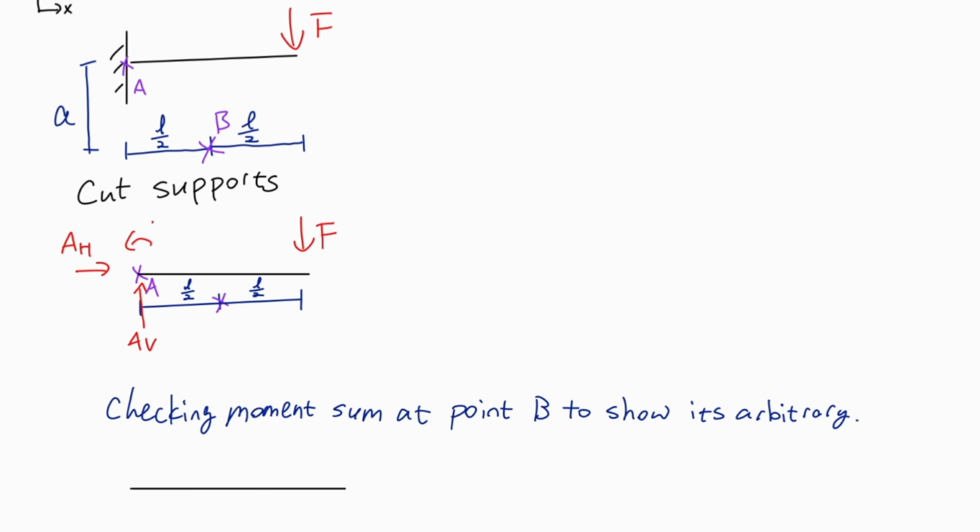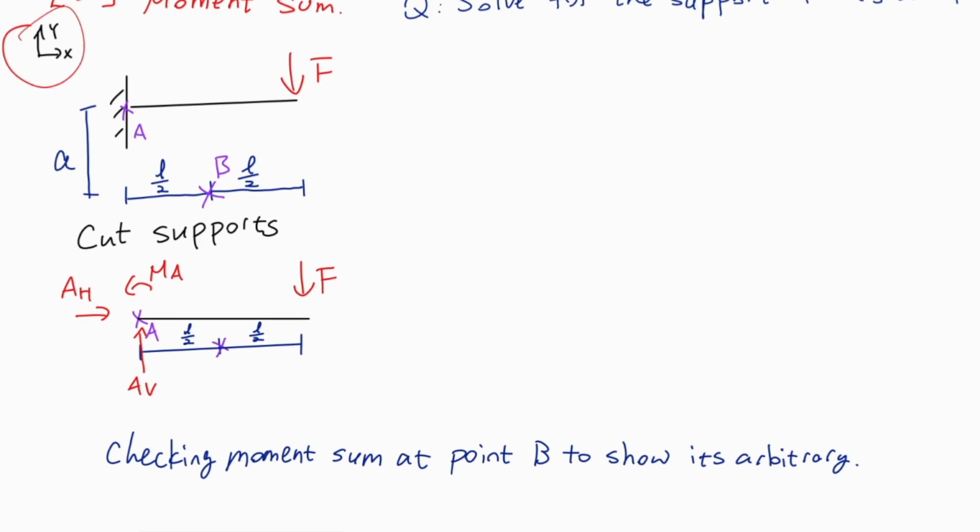Okay, these directions right now we can say are arbitrary, but if you are in an exam setting, please define them with the global coordinate system. So in this case, I'll draw it right here, just to say that I want my support directions to be the same as these two. So I have x, y, and if you have learned the right-hand rule, you will know the z direction is in this direction, and if you do your curl, it should be this direction that's defined as the positive z direction, which refers to my moment direction.